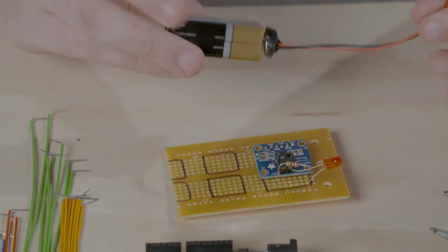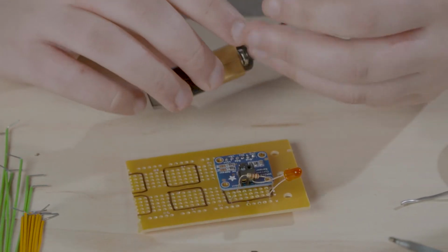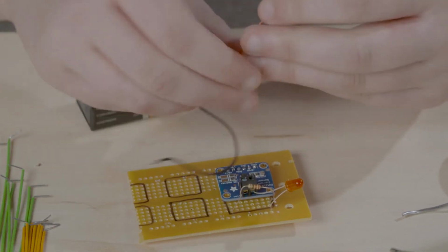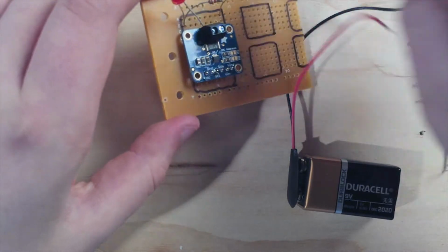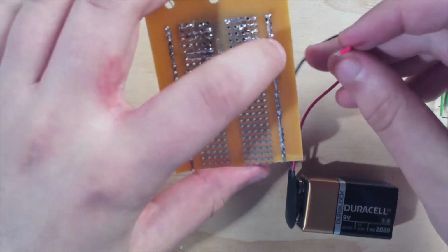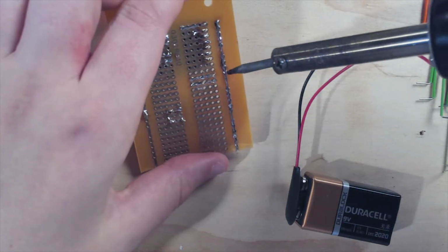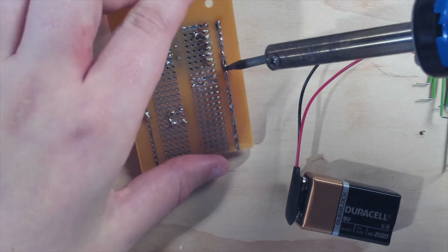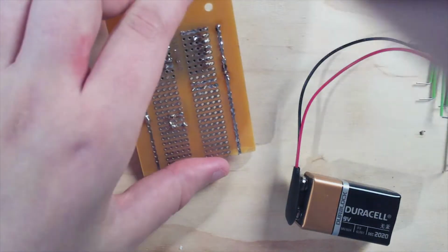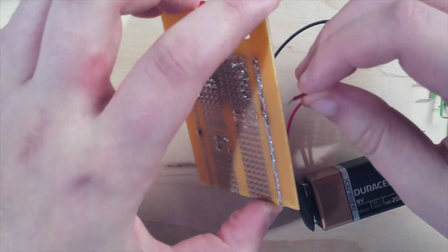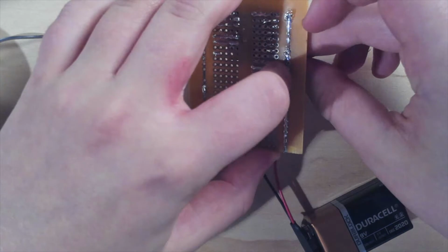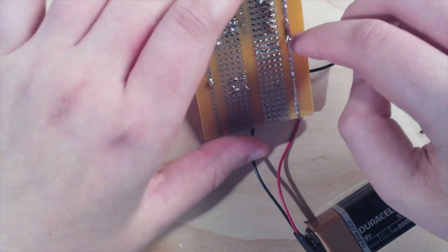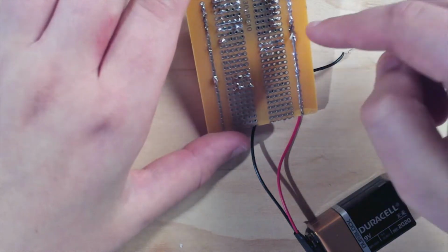Now, let's add the 9-volt battery in and establish our positive and negative for the circuit board. We'll have the positive going on this side and the negative on this side. Let's flip that around. I can see that I have some solder, so I'm going to unsolder a place here. There. So let's put it in there. Yours shouldn't have any other solder here. This is just some stuff I worked on before, so it should be a little easier for you.